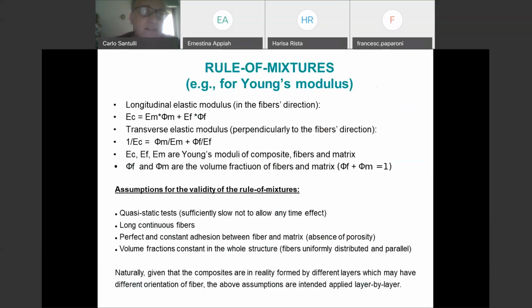First of all, think of a tensile test. I don't move that fast. Time makes a difference because you might easily understand, you may remember creep in metals. We have creep at high temperatures. So creep is the influence of time over mechanical behavior. In the case of polymers, polymers have got creep also at room temperature, at low temperature, etc. So I make a number of assumptions which are not realistic in any sense, but they are useful to make calculations. So I don't pull that fast, and this I can do. Of course, this is good in test. I cannot know whether in service a fast tensile load occurs.